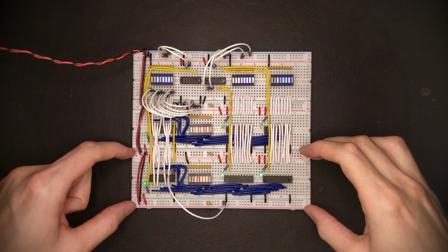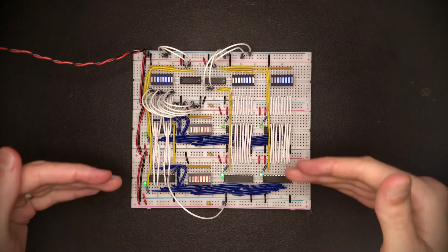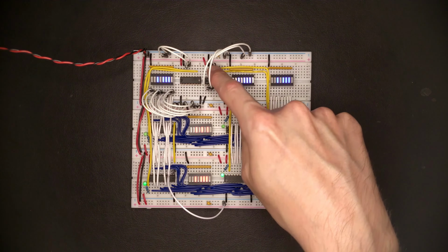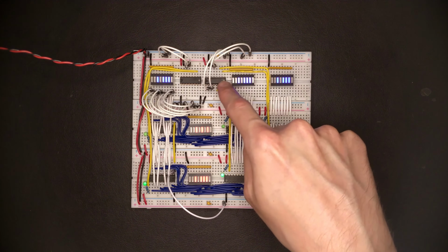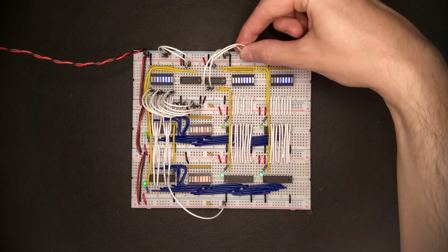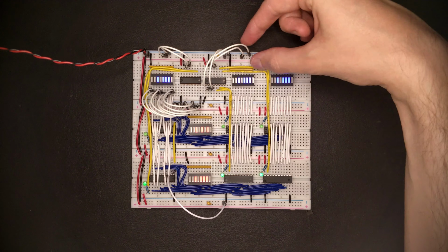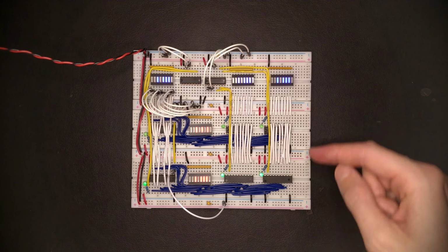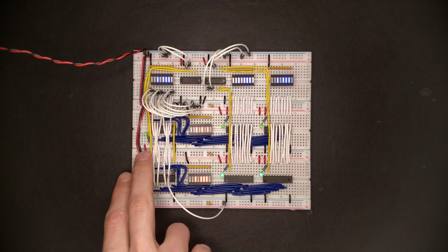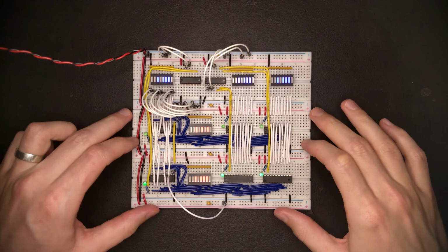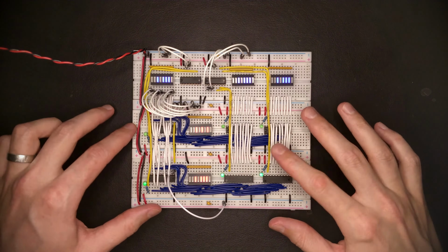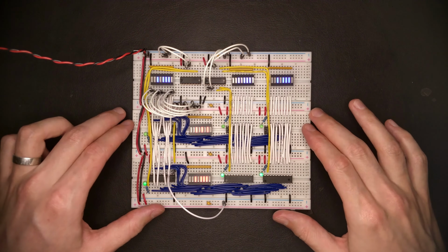And as you can imagine, we could just keep going and replicating registers and just add them to the stack. And as long as we find chips that can convert binary numbers into these one-hot encoded signals to produce the output enable signals, we can have very convenient addresses here that we can change in order to select which of the large stack of registers should actually be read out or which of the registers should be written to. But for the time being, I think just 2 registers is quite enough, and we can use that to get started with some of the instruction encoding business, which is also super interesting.